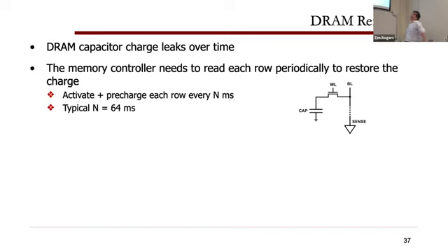Okay, you guys should really know this, but let me just very quickly go through it. Let's talk about the cell itself. A DRAM cell is different from an SRAM cell. How many transistors are in a traditional SRAM cell? 6. Thank you, VLSI people. Everyone who does any kind of EC or EE should know this. It's a 6T SRAM cell: you've basically got 2 inverters and then some controlling transistors.